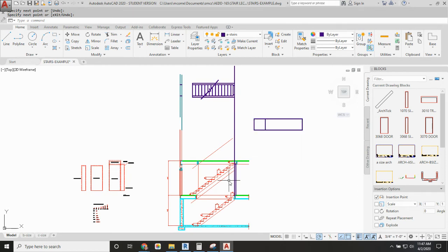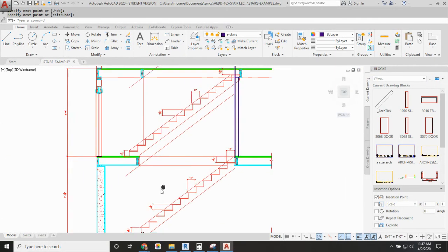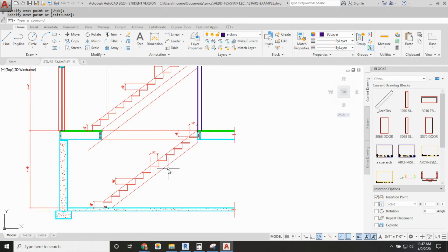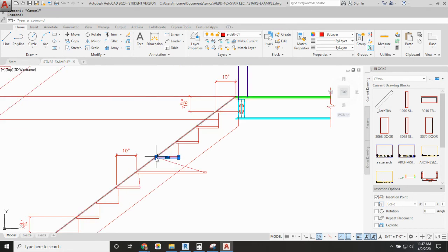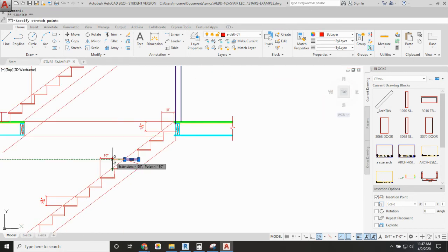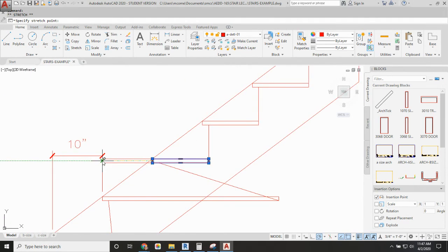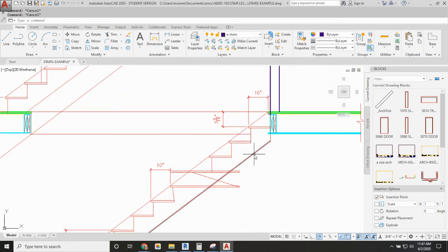And whenever you're designing stairs, regardless of if they're L-shaped, U-shaped, whatever, those stairs are going to be designed first as straight stairs based off of the same dimensions that we used. And then what you can do is take one of those. Let's say we wanted to make a landing here. I would increase the width of that so that it was 3 feet wide, and then the stairs from then on I would see beyond. So this is how I would generate an L-shaped set of stairs. See how the dimensions and where your landings are aren't going to change. It's just that the stringer configuration